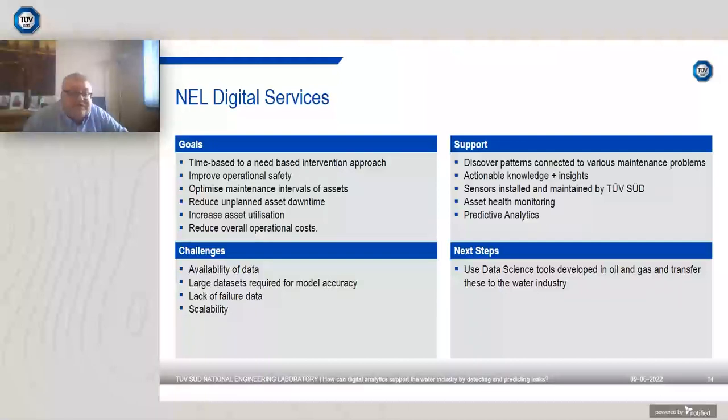By combining the facilities of the UK's national standard for flow measurement with emerging data science techniques, we have been able to provide end users with a means of interpreting meter-specific diagnostic data and relating the response on the said data to specific operating conditions. The experiments and data science techniques utilised to produce the above results can be deployed to address specific end-user requirements on a case-by-case basis, as well as form the foundation of a much larger condition-based monitoring system. These approaches can also be used to provide the back-end functionality to a much simpler interface that simply tells the user what the prevailing fault condition is.